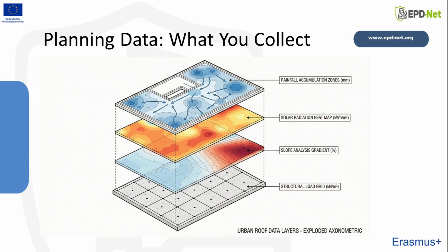For energy, archetype buildings with typical schedules are common. Context matters too. Shading, wind exposure, and urban heat island hotspots change the expected benefit of greening a specific roof. If you cannot get a parameter from tests or product data, record where the number came from and run a sensitivity range so the result is not held hostage by a guess.